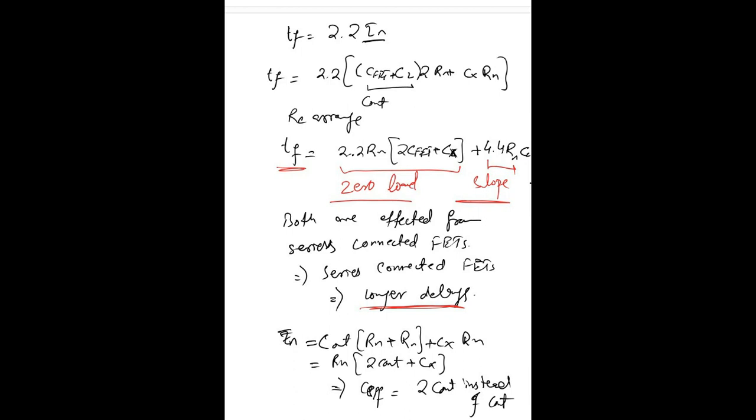And then in the second video of this series, we calculated the rise time and fall times, and also saw the power dissipation, the maximum frequency limitations, and the different features of the inverter. And in this session we have explored how we can apply the same calculations or the same phenomena of an inverter circuit to different MOSFETs.